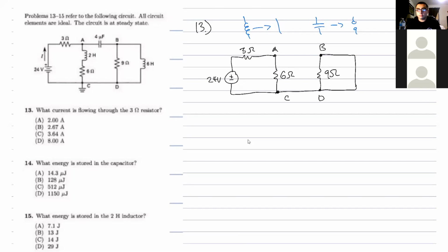Yeah. Because this is shorted right here, and this opens, and this shorts right here. So that just turns into a very simple circuit now. You see? Okay, so now we want to find the current flowing through the 3 ohm resistor, which is pretty much just the current in this loop. If we were to just find the current in this loop, everything's gonna be okay.